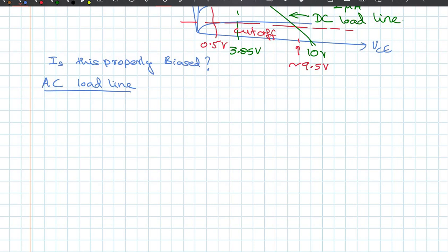So almost all of it goes to the capacitor, right? So in order to do this, if you are doing a design, we have to choose the capacitor in such a way that the capacitor impedance should be at least 1/10 of the resistance of the resistor which it bypasses. So that's what you need to do. So in that case, assuming it's close enough, we assume these capacitors are short circuits.